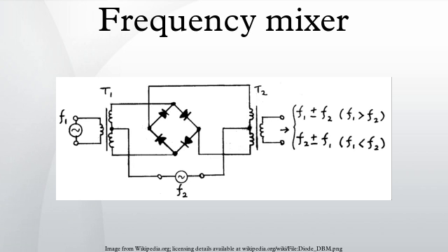The mixer circuit can be used not only to shift the frequency of an input signal as in a receiver, but also as a product detector, modulator, phase detector or frequency multiplier. For example, a communications receiver might contain two mixer stages for conversion of the input signal to an intermediate frequency, and another mixer employed as a detector for demodulation of the signal.